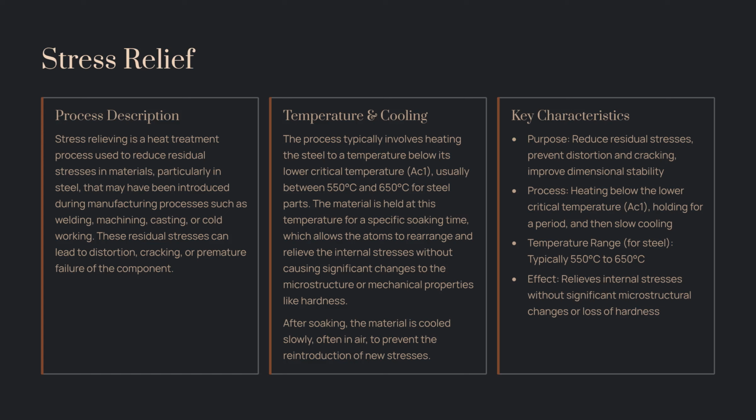Stress relief. Stress relieving is a heat treatment process used to reduce residual stresses in materials, particularly in steel, that may have been introduced during manufacturing processes such as welding, machining, casting, or cold working. These residual stresses can lead to distortion, cracking, or premature failure of the component.